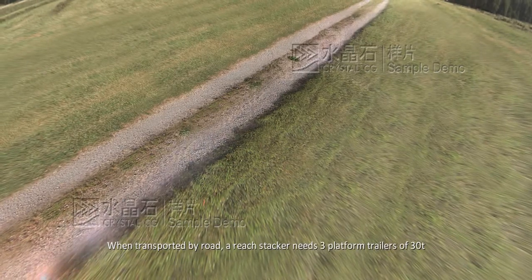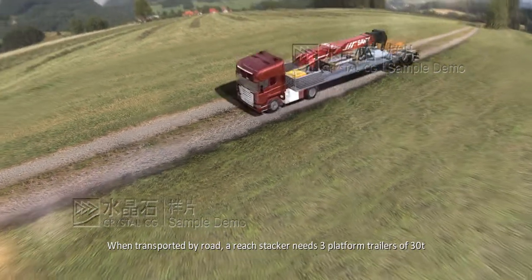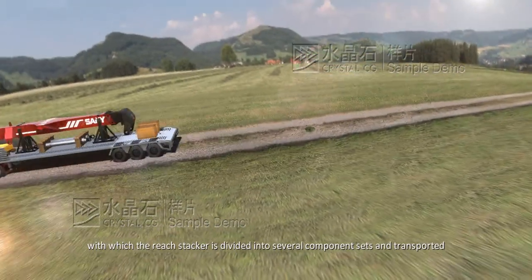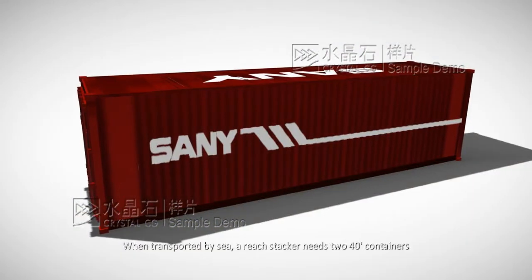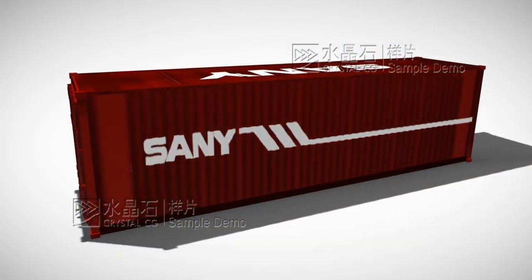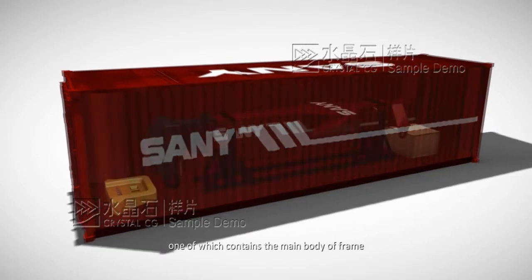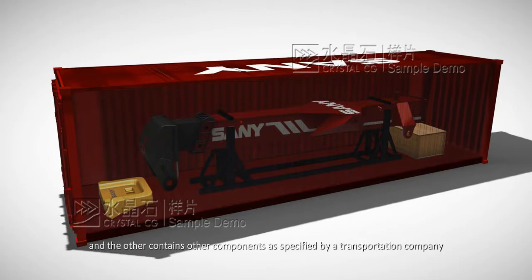When transported by road, a Reachstacker needs 3 platform trailers of 30 tons, with which the Reachstacker is divided into several component sets and transported. When transported by sea, a Reachstacker needs 2 40-feet containers, one of which contains the main body of freight, and the other contains other components as specified by a transportation company.